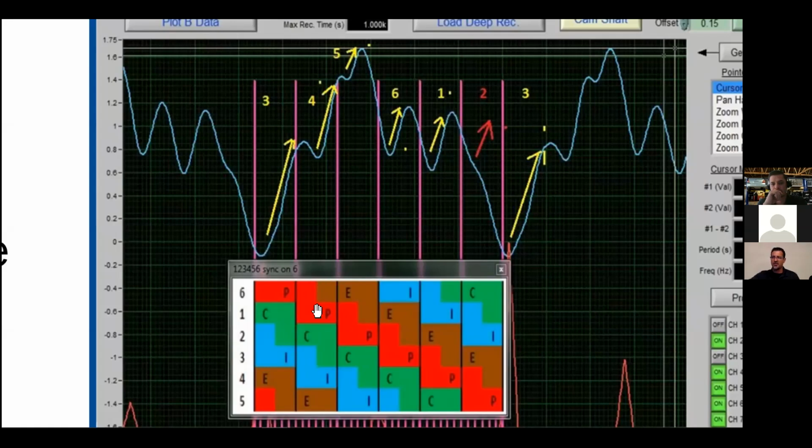So from here to about here, the crankshaft increased in speed. So if I'm creating vacuum here, let's pretend I put a gauge on this. If I'm inhaling air, if I pull slow enough, that gauge won't move. If I pull faster, I will start to build a vacuum. If I pull down rapidly, the vacuum gauge is going to go way high, right?